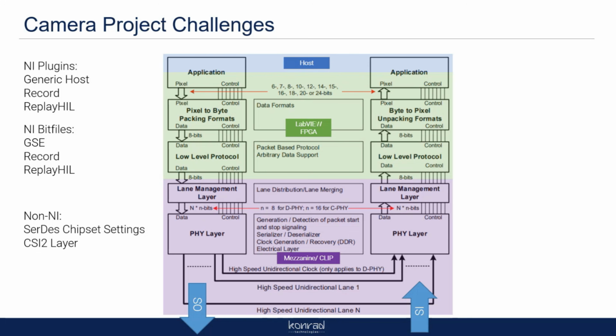Hardware in the loop. Yeah, this is good stuff. The biggest thing too is synchronization. It's crazy to think about, but with some of these algorithms, if the data's off, it's not a valid response. If you've got a radar saying one thing and a camera saying another, but they came in at different times, who do you believe?